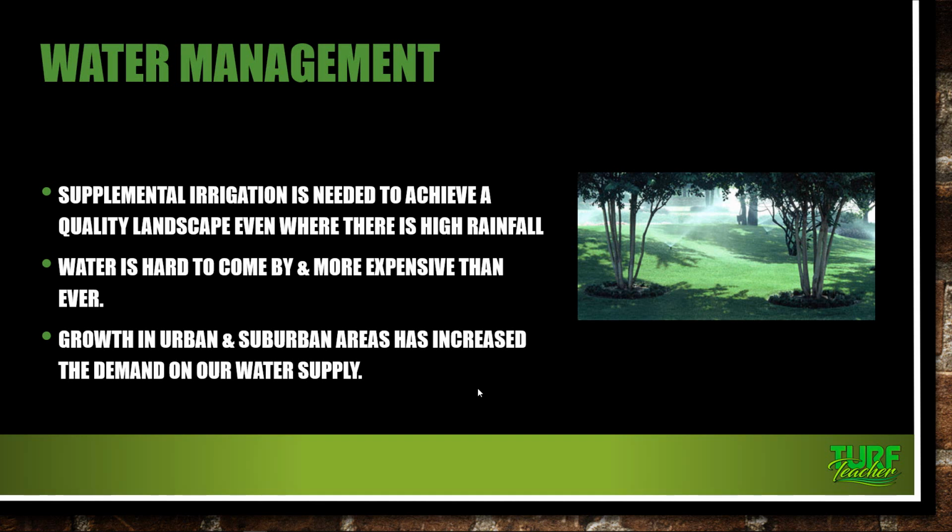The clay soils everybody thinks are really good, and I'm from the Piedmont here in North Carolina. I love red clay soil, but guys, guess what? Clay just holds those water molecules so tight that not all of it is available for our plant materials. And people kind of laugh at this when I say it, but plants are able to get more water from a sandy soil, even though it percolates through real slow. But the sand